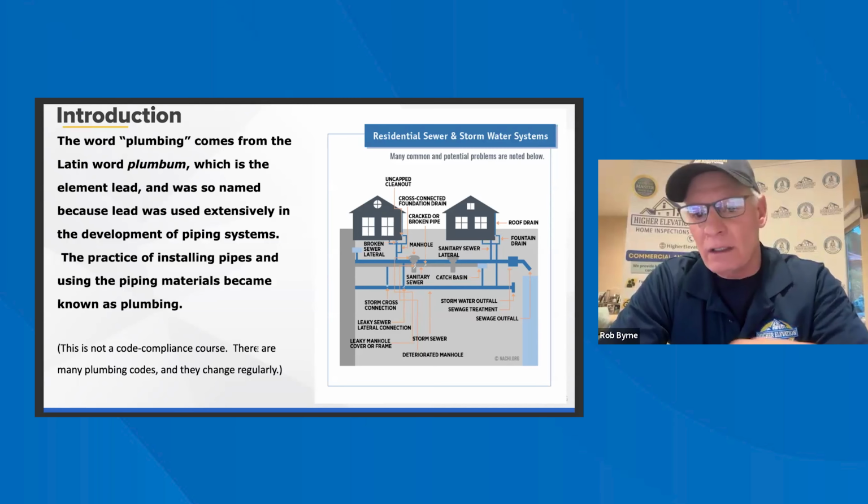Tankless coils from boilers. Understand that some boilers have the coil inside of it. So this is more in the field practicality. You can see that's a coil going inside the boiler. So tankless coils used for heating home steam or a hot water boiler produce domestic hot water as well. No separate water heater tank is used. Understand that, because when you go to a house, you might not have a water heater, but you're going to get your hot water through the coil on the boiler.